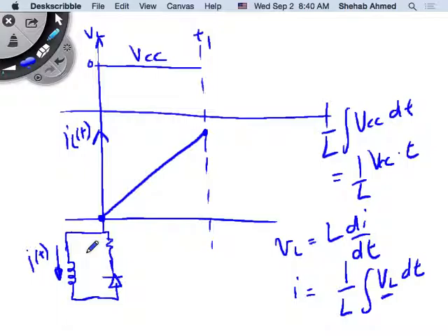So this is a circuit where you remember the T equals 0 conditions that you were talking about in 214. You have a circuit, and I close the switch at T equals 0. The inductor had a certain current through it. This is the initial condition, and you were solving the circuit, right? So the solution to this was a first order differential equation. We will go through that in more detail, but for now, the solution to this, if you remember, this was an RL circuit. The solution to the current I of T was equal to A e to the minus T over tau, where tau is equal to L over R. Remember that? Very long time ago, 214.